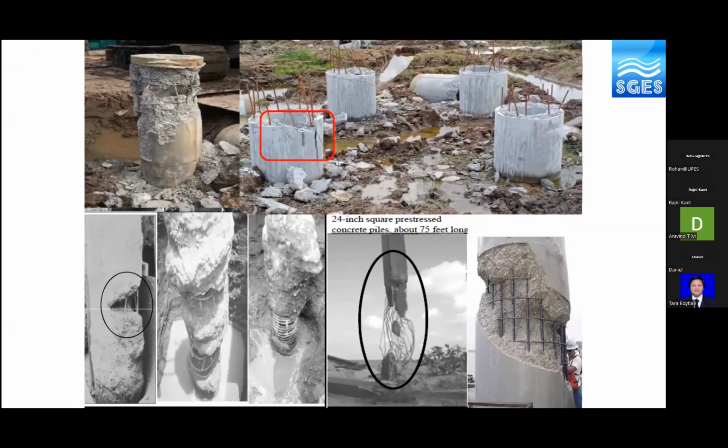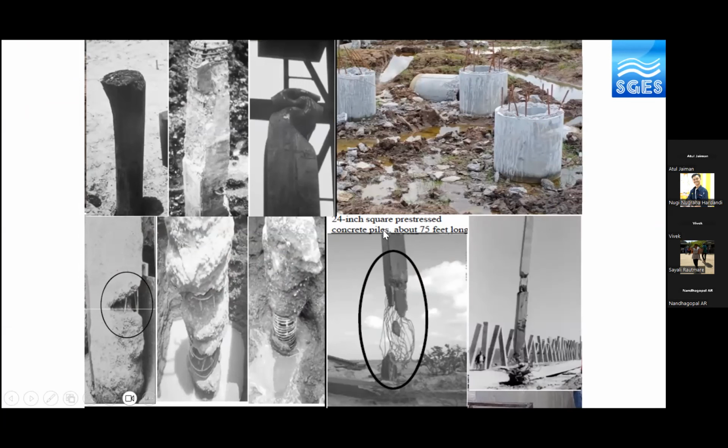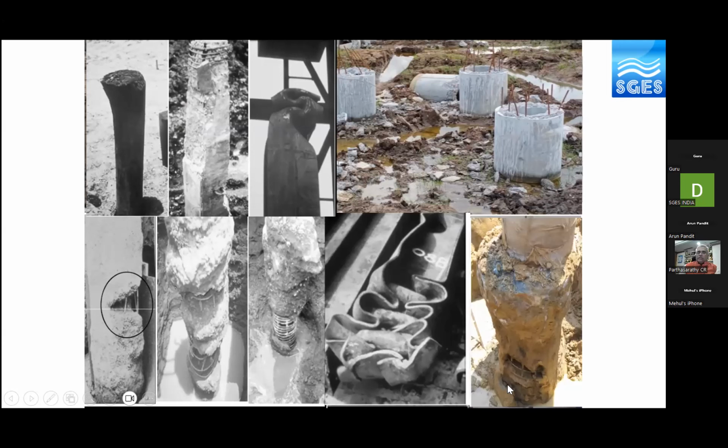During the construction of deep foundation, there are several anomalies that we witness. The pile top can be damaged. There is a severe necking in the pile, the bleeding in the pile. The pile toe could be damaged if it's a driven pile, severe defect. Even steel piles have the same problem. If the stresses are not controlled during driving, the piles could be broken somewhere along the shaft. The toe damage for a steel pile driven to rock. And you can have serious defects in any of the pile elements, even for the drilled shafts.